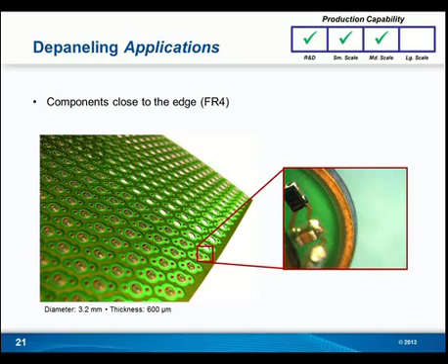But now there are also lasers available in the market that have quite a bit more power and that are more suitable for cutting FR4 that's maybe 1.5 or 1.6 millimeters thick. So it's 62 mils thick, which really opens up the door to some new markets and some new applications. And the great news is that you keep the same quality of the cut, even though you're using more power. Your sidewalls are still going to be very straight, and you may have a little bit more charring because you're using more power, but not so much more charring as to affect the part in any way.